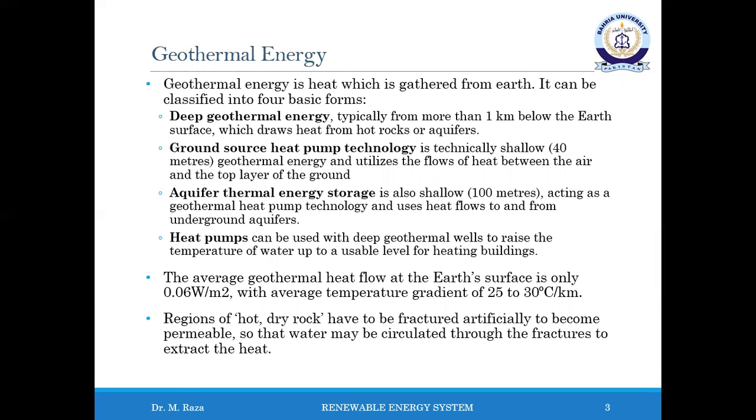Ground source heat pumping technology is shallow, about 40 meters depth, geothermal energy and utilizes the flow of heat between the air and the top layer of the ground. Aquifer thermal energy storage is also shallow, about 100 meters, acting as a geothermal heat pump technology and uses heat flows to and from underground aquifer. Heat pumps can be used with deep geothermal wells to raise the temperature of water up to a usable level